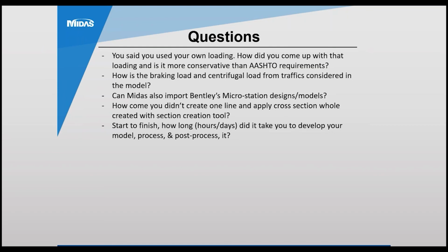How did you control or enter the transverse stiffness between the box girder pieces? Oh, okay. So I wish I could show you, but in the MIDAS model, for your sections, if you define your dummy beam between the girders as a value type, then you can manipulate any of the properties that you want. That's basically what we did: gave ourselves the option to change the properties as needed. I hope I'm answering that question right. But that's essentially how we handled that, and those were based off of the NCHRP report.